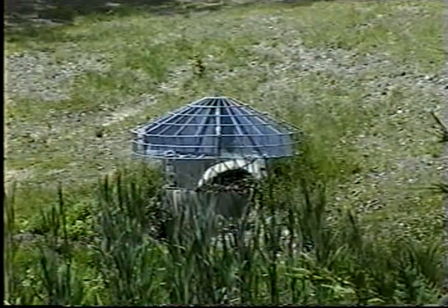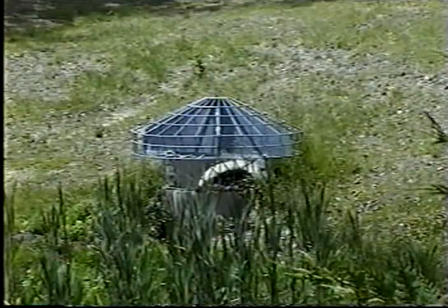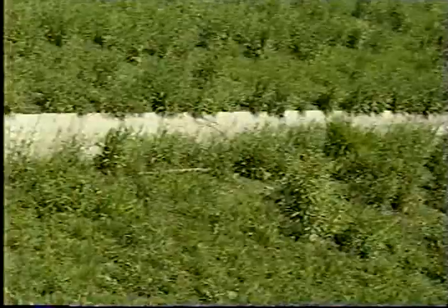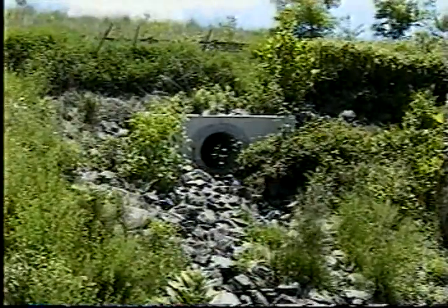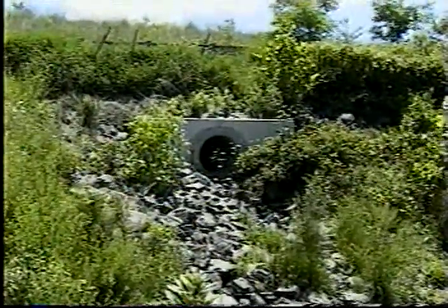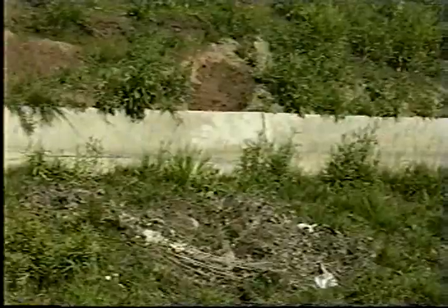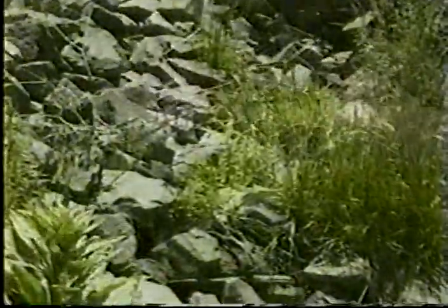behind the backslope can supplement the system. Vegetation or erosion-resistant material should be used on side slopes. Bank protection is required when stream flow or wave action endangers highway embankments or structures. Erosion may be controlled by rock slope protection, grouted riprap, or other materials available locally.